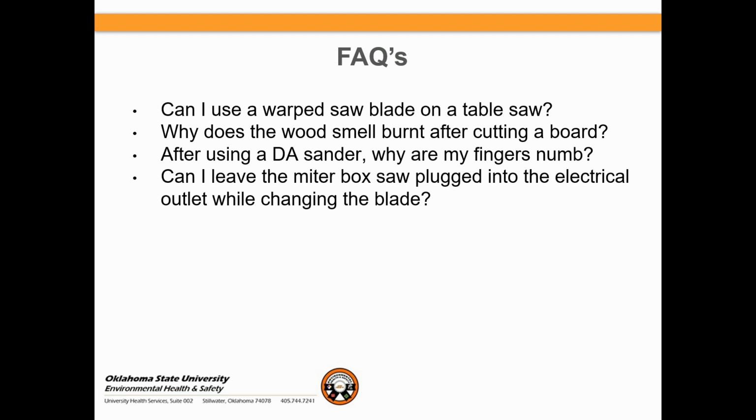And why does the wood smell burnt after cutting a board? Remember, at the very beginning we talked about dull circular saw blades, for example, or maybe table saws. This is what we're looking for here. Don't use warped blades, please. Get the blades replaced. Not only that, if it's warped, you get a lot more vibration coming through the handle. But the other most important thing is,